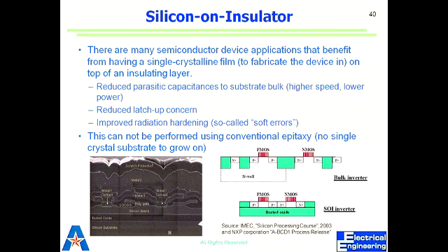Generally, you don't want to bond them to electrically get something out of the interface. But you now have double-sided devices. So you can have a micron thick oxide layer in the middle of the silicon. Yes, that is what you do in SOI wafers. You have silicon dioxide there, which is amorphous and now merged, and on either side you have crystalline silicon. So essentially, yes, you're right. You don't want the interface to be electrically active, but what it brings is flexibility to work on both sides.